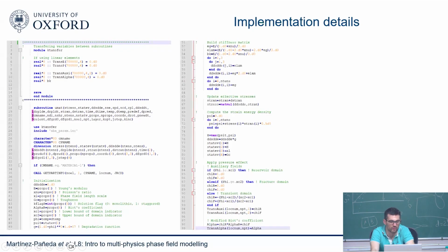So it's similar to before. You build your elastic stiffness matrix, identical to before. I'm using Lamé parameters, Young's modulus, Poisson ratio. Using the usual expressions, you build here your stiffness matrix. Exactly the same as before, as we discussed the other day. You update your strains. So you have a strain is strain plus increment in strain. Abaqus is giving you the increment strain. This is all integration point quantities. You calculate your stresses. It's multiplication of the material stiffness matrix with the strains.